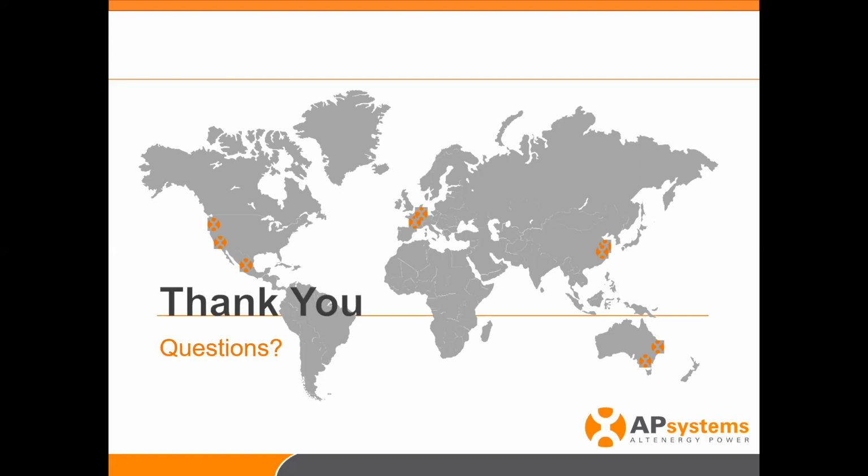I think it was a 405. They went through the testing and the state of California says, well, it's a 405 STC, but it's actually a 305 PTC. So like I said, do your research, ask your module manufacturers or your distributors, find out what the real world expectations are, and then make your inverter decisions based on that.